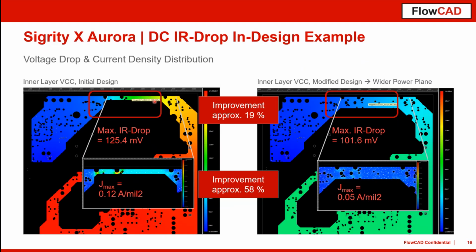If you analyze such a design on a first-principles basis, you may see, okay, this could be a bottleneck, but I'm pretty sure that you would not see that there are some additional vias here that narrow the path additionally. Using the current density, it becomes quite simple to see that we have a very, very small path where the whole current has to go through.